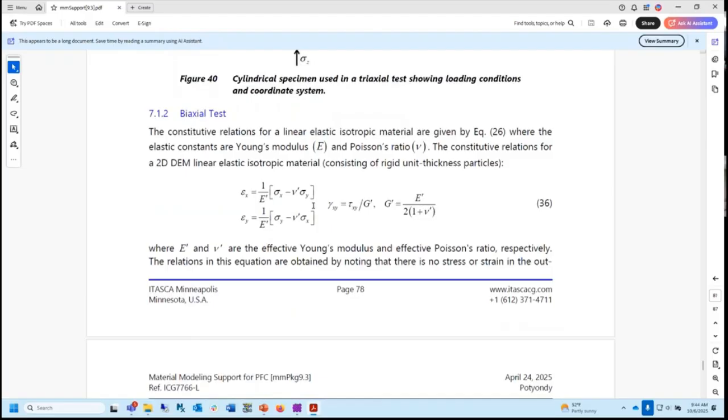You could say it's plane stress because there's no stress touching the ends of those cylinders, but you could say it's plane strain because it's not straining either, because the cylinders are rigid. They don't bulge out. And it's the fact that they bulge out that makes plane strain affect things. And so it's not a 3D continuum. It's a bunch of cylinders. A bunch of cylinders are not a 3D continuum. So it's this weird interpretation problem.